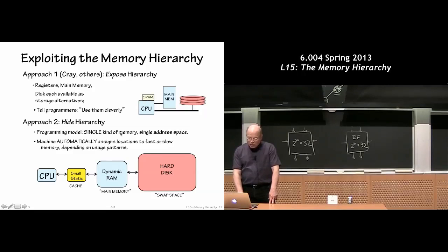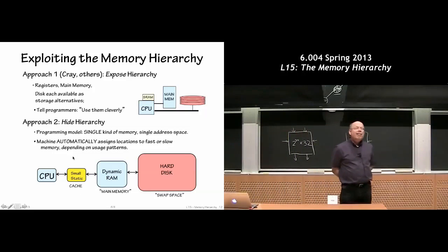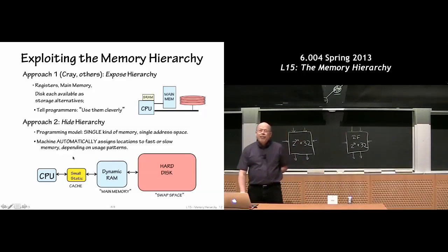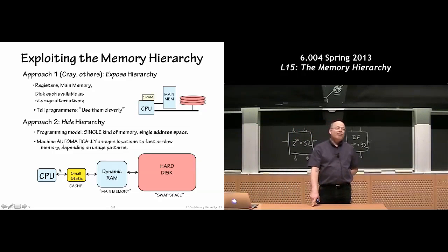As it turns out, we can fake what we haven't got, and that's because we're behaving rationally. It is possible for us to build hardware that will automatically manage where a particular memory location can be found, where you don't have to think about it. So you just access memory like you normally would, using addresses that your program generates. And the hardware will look over your shoulder and say, I see what you're doing. You're starting to read from the foo routine. Maybe I'll get the rest of the instructions of the foo subroutine into fast memory, into a fast program memory.